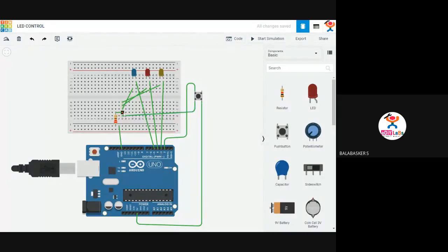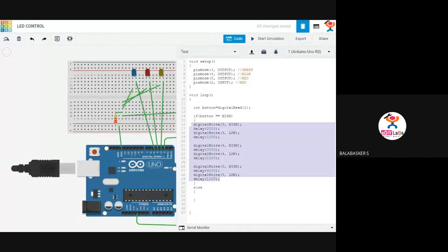Like you check it over the switch button. One end is connected to the ground. Here you can see the terminal is connected to the ground. That ground is connected here. So this side is internally connected to this end always. So this ground will flow from here to here. So always, without pressing the switch, my pin is connected to ground. Ground is nothing but low. And on the other end I have connected a 5-volt pin. So whenever I press this switch, all the 4 pins are short circuited, and this 5-volt will flow through here to the second pin. And automatically the high level is initiated. Whenever the high level is initiated, this task will be done. After completing this task, it again checks for the button. Okay, this is the coding.